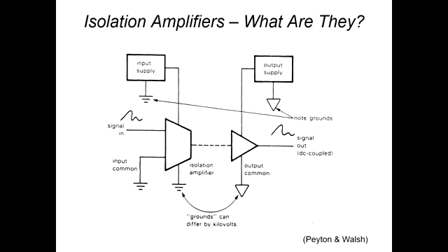And we're developing up another symbol, as you can see. There's always a different triangular symbol for any of these things. The isolation amplifier is like a big triangle again, with a gap in the middle. So we've still got a triangle here, but now we've got a bit of a gap in between. That's an isolation barrier, and usually it's of hundreds of volts isolation, so that we can separate two supposed ground points.